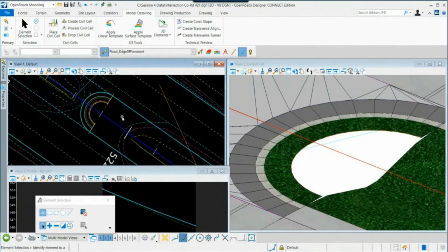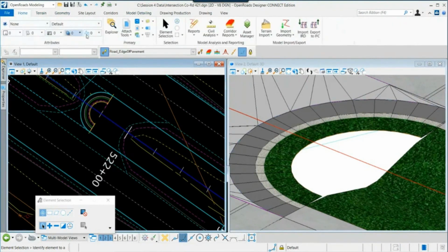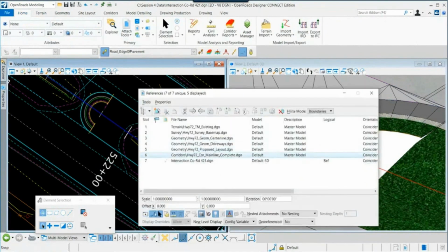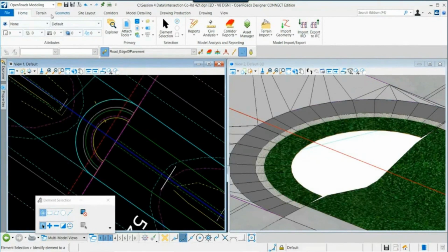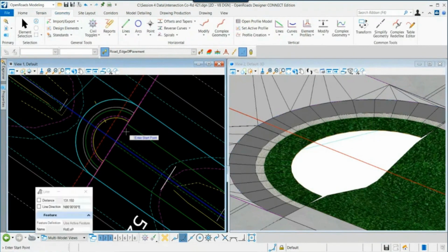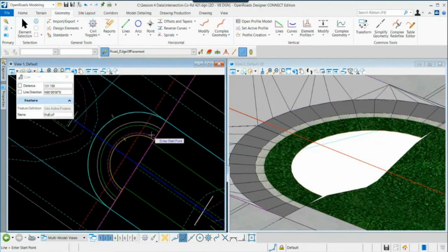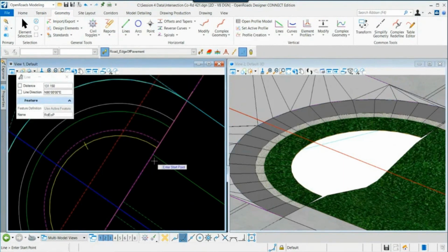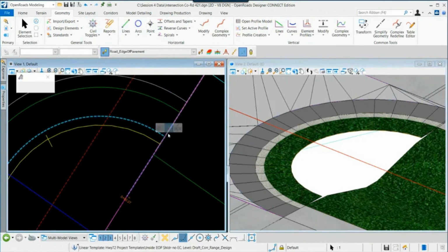Okay, let's turn on the corridor in the plan or the first view. So I'll go back to home. Let's turn on the corridor here. And what we're going to do is create just a quick horizontal element. And I'm going to define a profile along this section of the ditch to incorporate what we kind of have called a mini terrain to fill in this area. So using this, I might need to edit that template. I'm looking at the offsets here.